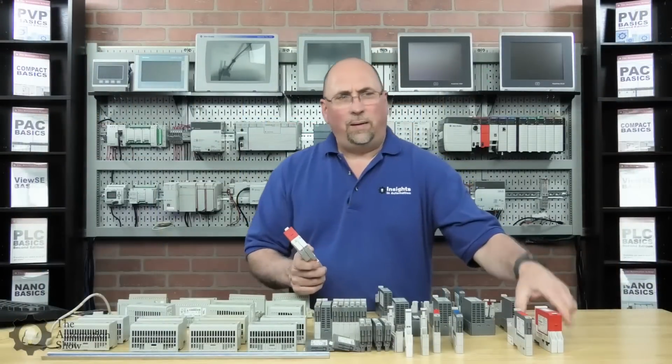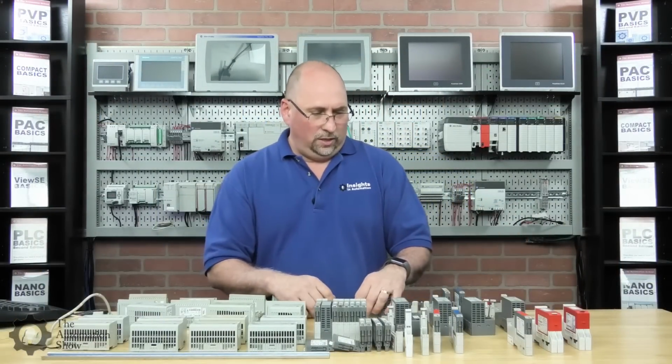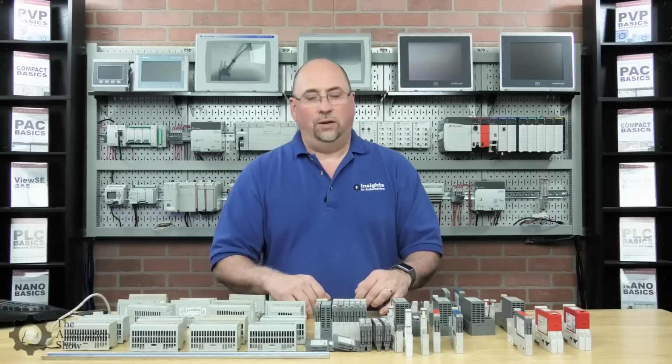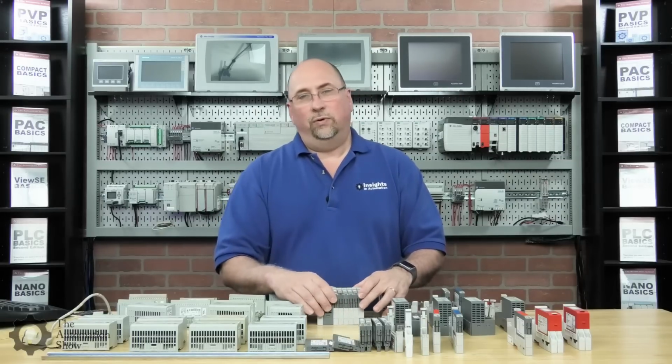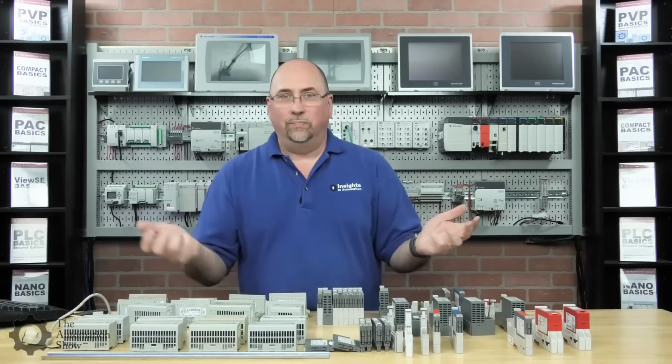And probably the last thing I want to talk about here is last state. I was unfortunate enough to be on site when a customer discovered that point I/O does not always hold last state. Now, you're asking, why would you want your I/O to hold last state when it loses connection with the controller that's controlling it? Well, let's say that I/O turns on fans, and those fans pull out dangerous, hazardous gases, right? That could, or pump out hazardous liquid, right?